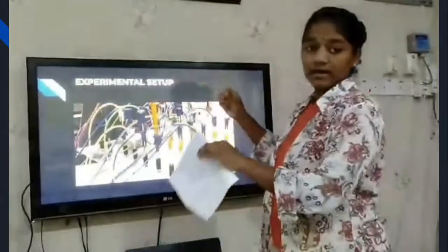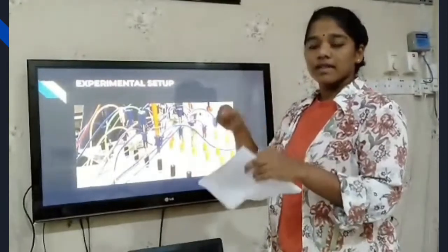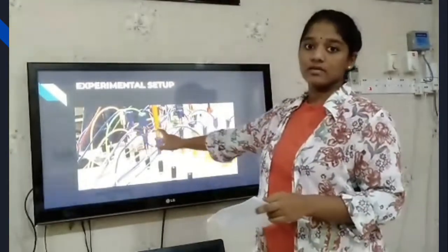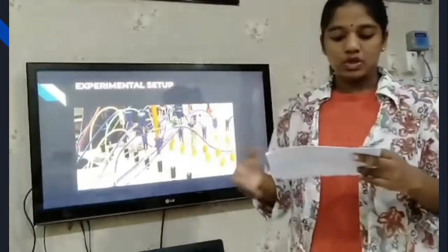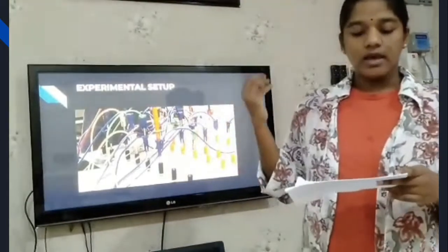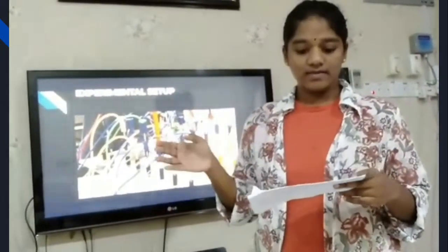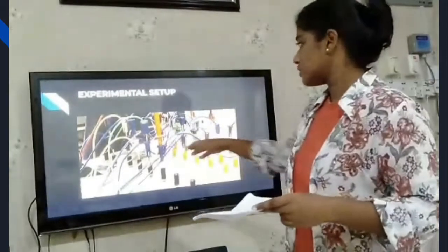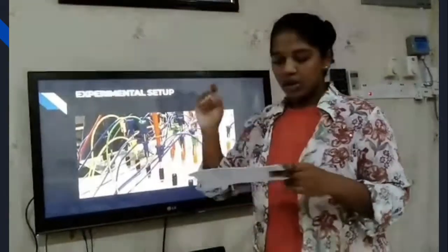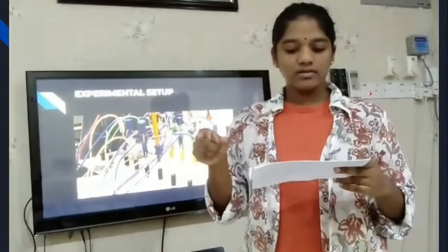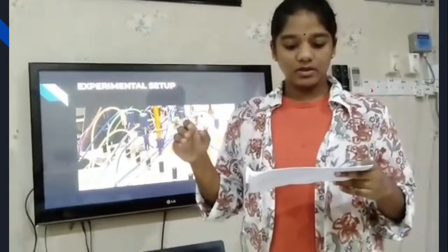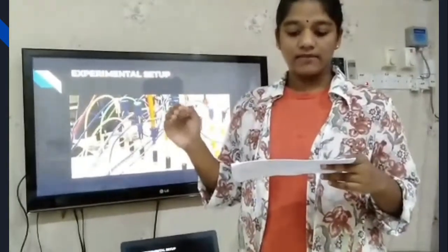In each stage, a multimeter will be used to measure the output voltage, so we could see an increase in voltage in each stage here. There are oscillating and smoothing capacitors in this circuit. Oscillating column capacitors are charged in a half cycle by the upward odd numbered diodes. There are odd numbered and even numbered diodes labeled here. The odd numbered diodes charge in one half cycle, and in the next half cycle, smoothing column capacitors will be charged by the even numbered diodes.